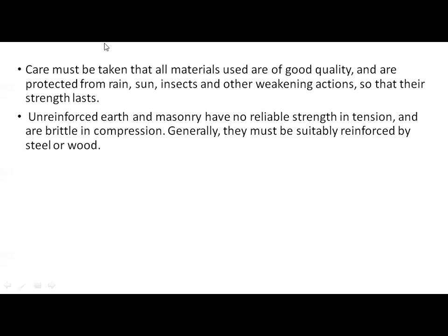Next one is: unreinforced earth or masonry have no reliable strength in tension and are brittle in compression. Generally, they must be suitably reinforced by steel or wood. Look, unreinforced earth or masonry have no reliable strength in tension.